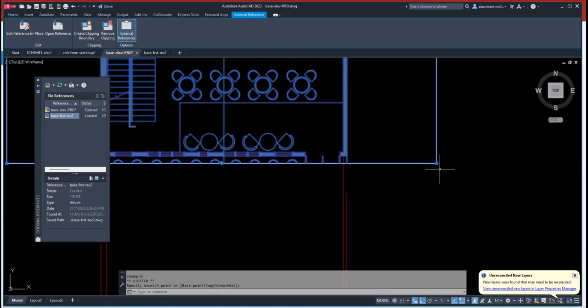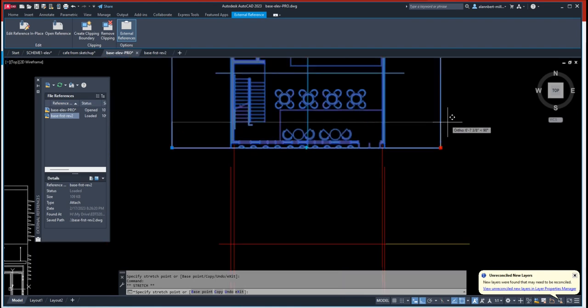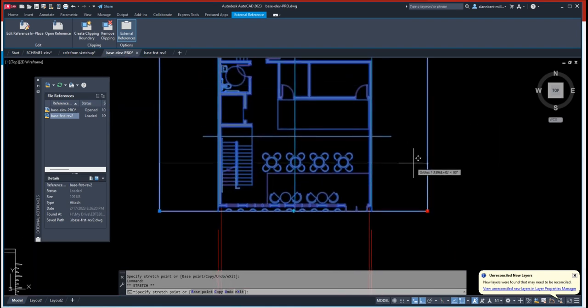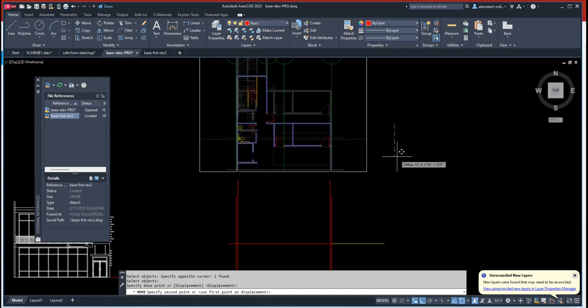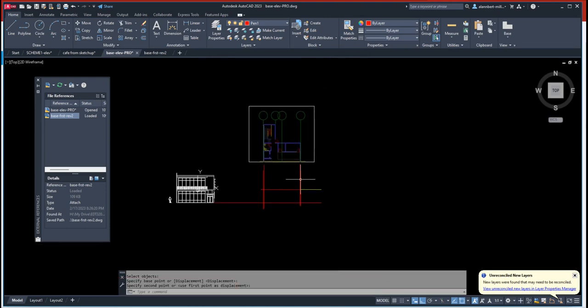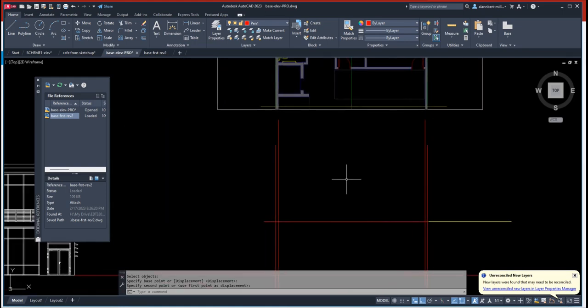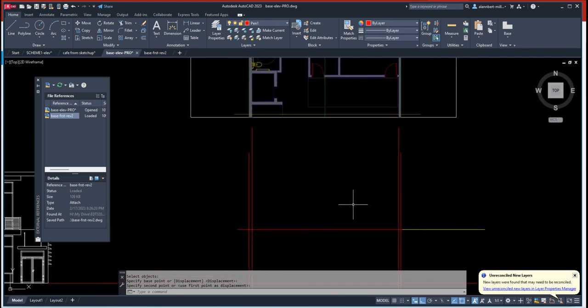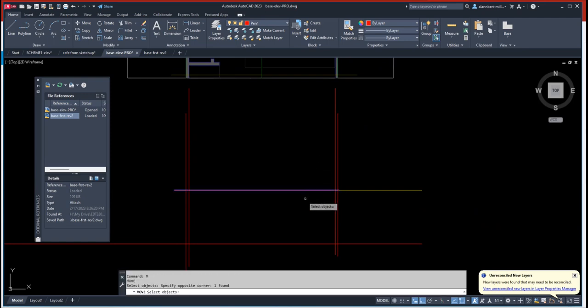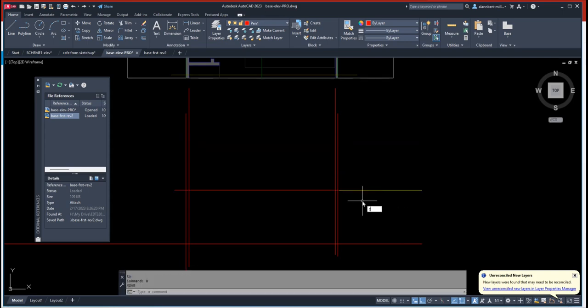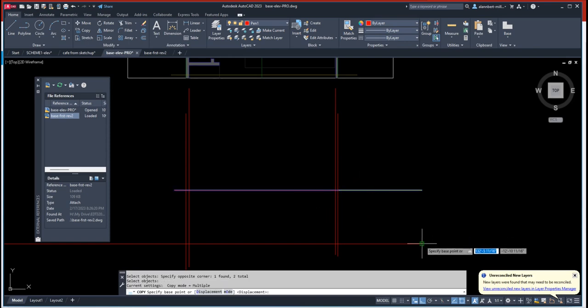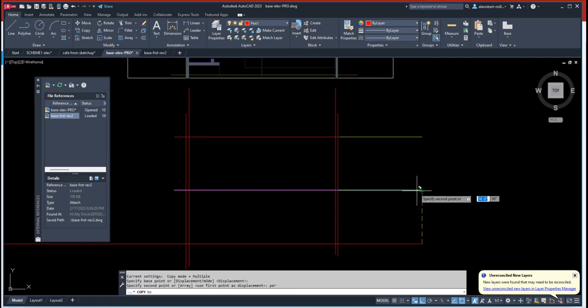So we can also do that because anything in front of your section line is not supposed to be seen. So you can do something like that. Okay. And that means that you can move closer to your floor plan. So that's called X clip. Okay. So the ceiling is another 14 feet. So I can simply just copy this and copy it 14 there. I thought I did a copy. There you go. Copy, or you can do an offset.